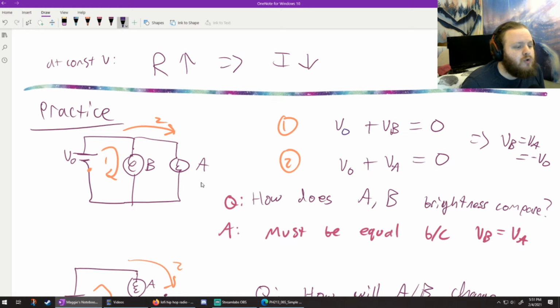If the two light bulbs are in parallel with one another, then they're providing less resistance to the circuit overall than one light bulb individually. And certainly less resistance than the two light bulbs in series with one another, if light bulb A was down here beneath light bulb B.